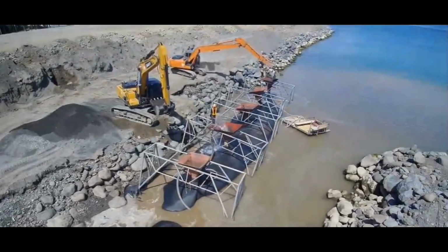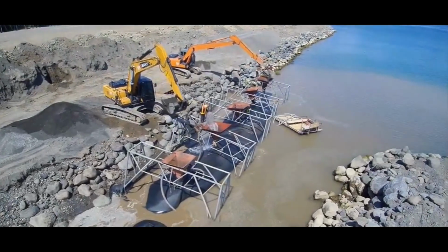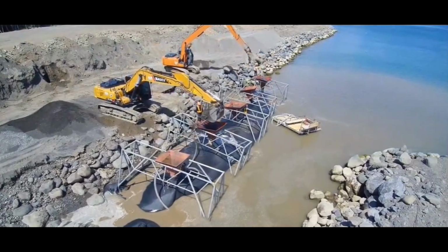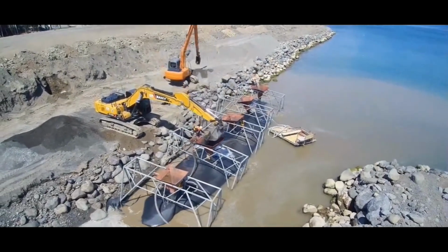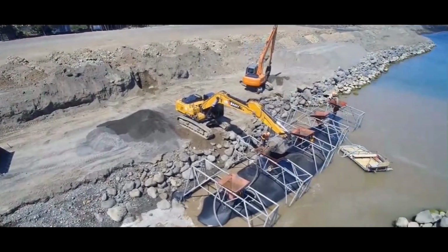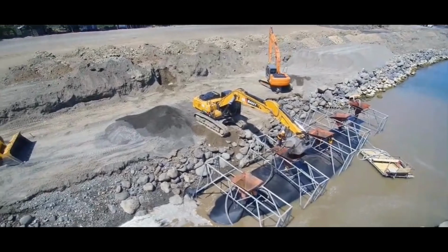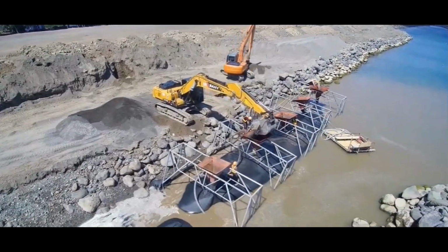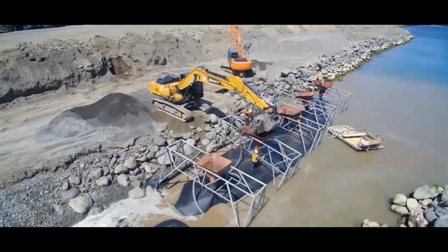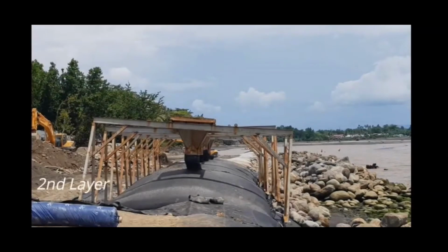After that, around 10 to 15% solid slurry is transferred through the piping system with constant adding of sand and water supply. In this piping system, there is a mechanical pinch valve which is used to control the flow at each fill port. Dynamic adjustment is required for the pump speed, slurry storage percentage, and number of fill ports throughout the project development. This is because the piping system changes in pipe length or structural combination as the project carries out from north to south.